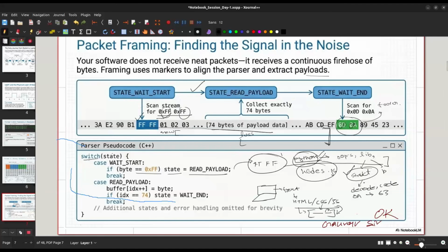Then we use PySerial. What do we use PySerial for? We use PySerial to receive the data coming from the USB port. Let's say your microcontroller is trying to send you 0a, 1a, 1b, etc. Your GCS will first take the data from PySerial and give it to struct, and whatever the decoded data is, it saves it and at the same time gives it to JS, and JS sends it to the HTML to update it. So in the front end, you will see altitude is equal to 23. Not so complex, right?